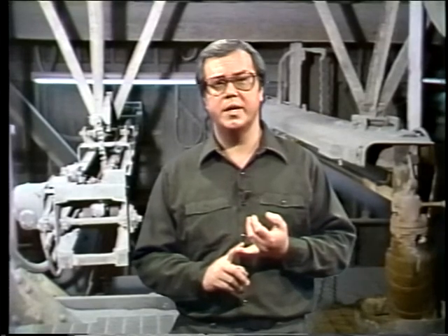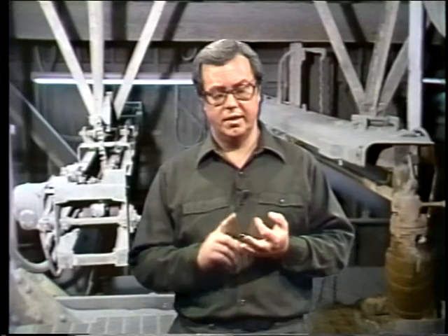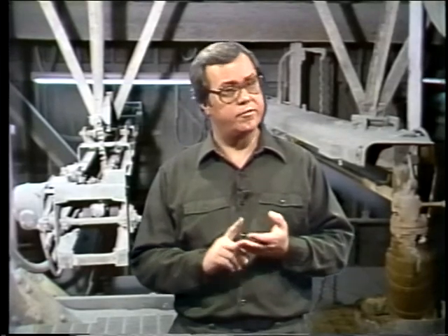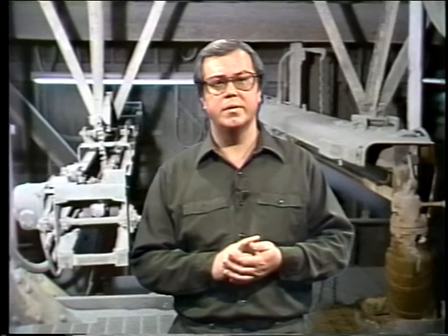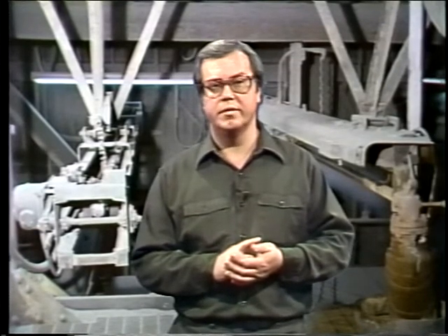1, they may fail to cycle properly. 2, on rotating and retractable soot blowers, the element may bind. 3, there can be excessive leakage of the blowing medium. 4, the blowing pressure can be too low or too high. And finally, number 5, nozzles can be blocked or the end of the element may be blown off. Let's take these one at a time.